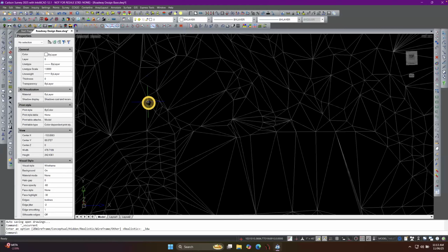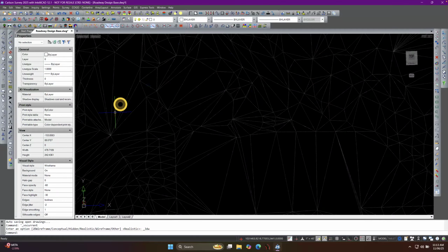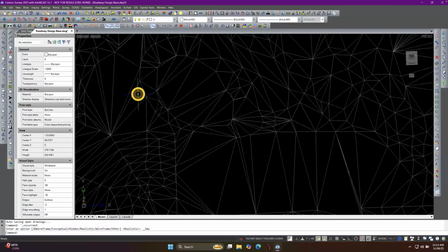You can see the shape of the original outline, follow my mouse here, and it has connected back. It sits here and sees that point, and then it looks around and finds points on these other contour lines and starts connecting up triangles between each of those sets of pairs of points. Okay, so that gets into the concept of using break lines and that sort of stuff.